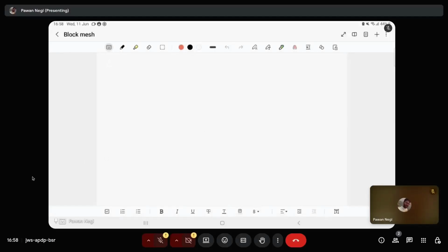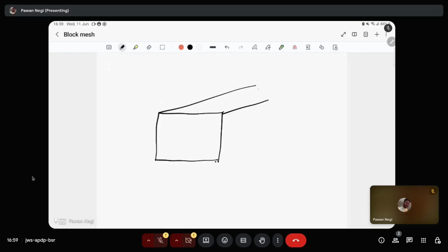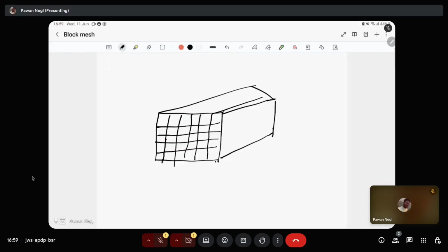Welcome back. In this lecture, we'll talk about blockMesh. Let me first introduce blockMesh. For example, you want to create a mesh for a channel which is a rectangle. The easiest mesh is to divide all the edges along the Cartesian grid. Right? Let's say you want a finer resolution along this edge, then you can create finer divisions near that axis.